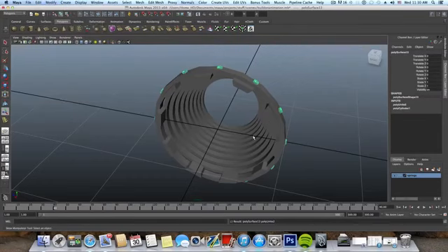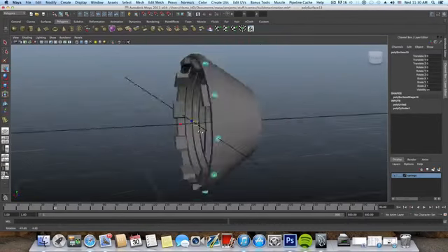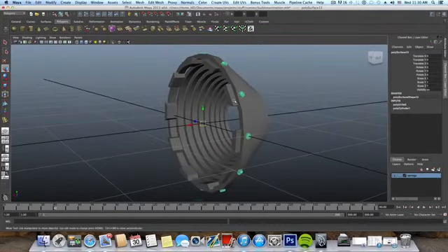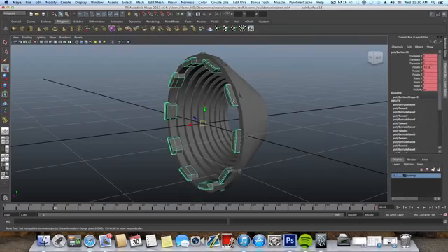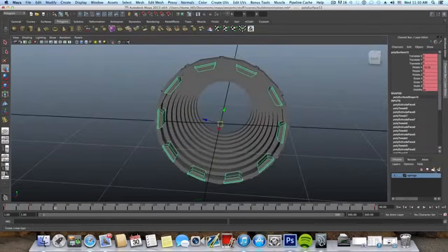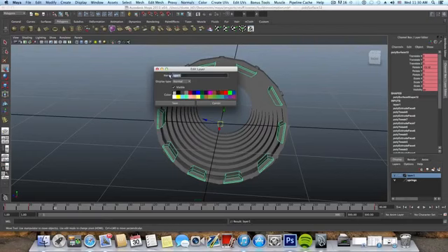Okay, that's great. At the same time I want you to grab these wings we created and add them to a separate layer. So click this while you have it selected, call it fan wings. Choose save, and just for now let's unreveal all of them.